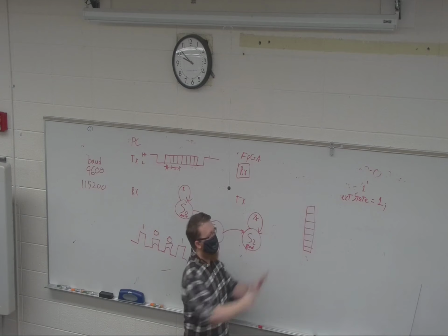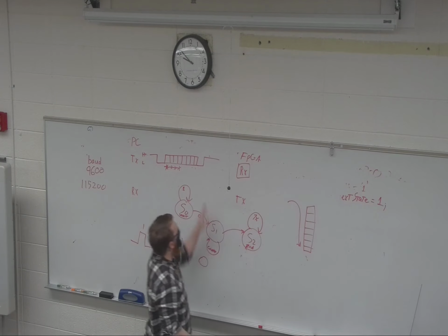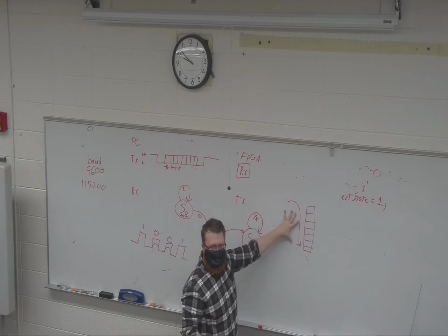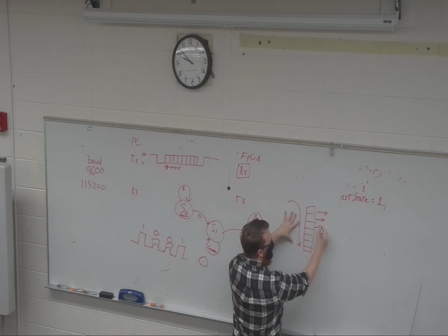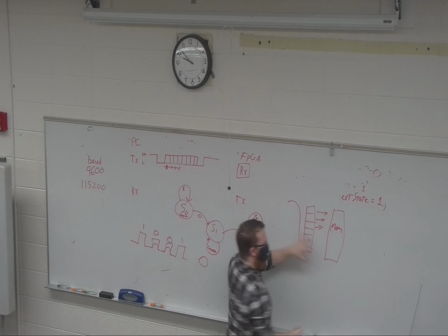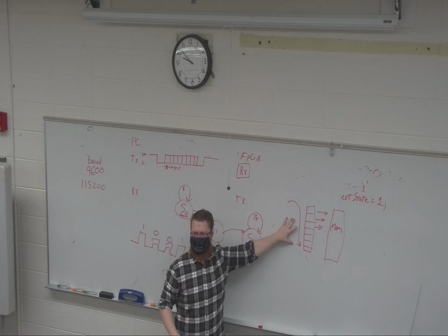You have some shift register, that data is going to pour in, load it up. You're going to get to the stop bit. During the stop bit, this guy's going to be full. You can use that opportunity to transfer all of this into some memory to hold on to it while the next process starts loading, while the next bit starts loading.